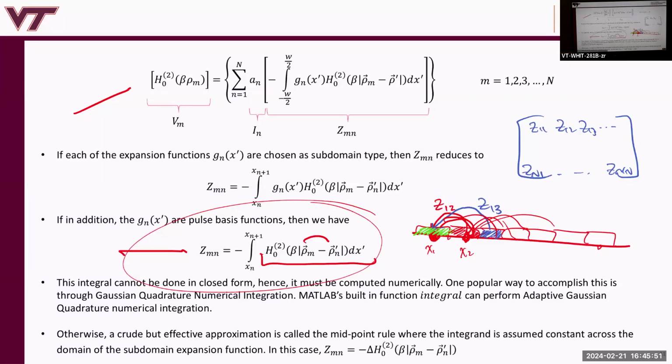So if you were to do that numerical integration with quadrature, you'd be breaking up that small interval into a bunch of segments and computing the Hankel function for each rho_m with rho_n. Quadrature means evaluating these matrix elements by taking this current and integrating over this domain. The Hankel function itself has rho_m and rho_n. It links the source to the observation point. Numerically, you'd have a bunch of rho_n's within that interval at which you perform the Hankel function evaluations.